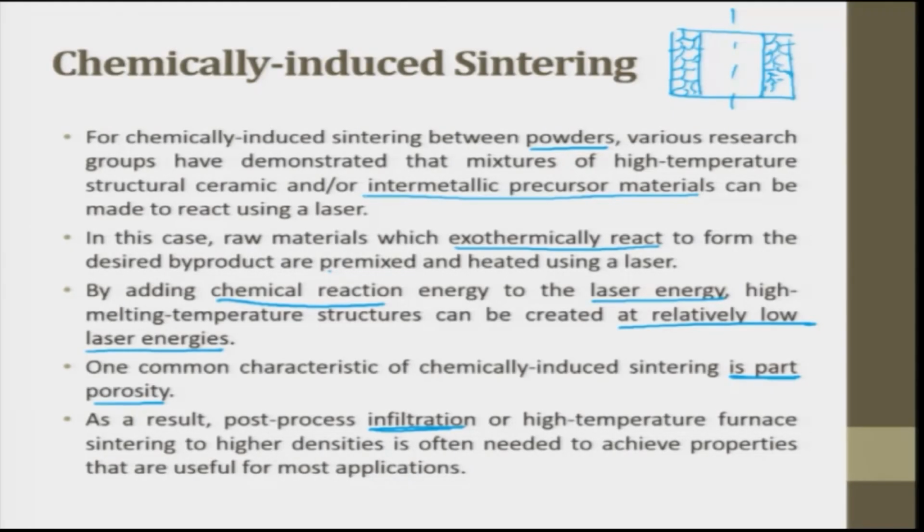So now what you do is, either you try to post process it, the bush once again, and try to consolidate it, or we try to infiltrate. What we do in infiltration, either we try to create a vacuum pressure here, allow the liquid from outside to enter inside, or you pressurize at very high pressures, you push the liquid in between the pores. So that process is called infiltration.